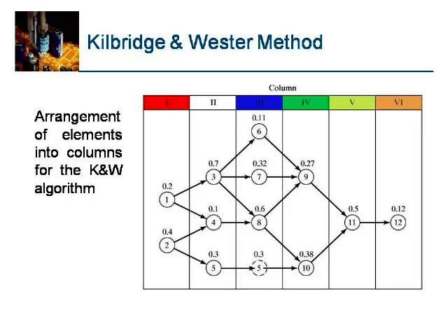So in this you can see here, we can draw lines as columns. This is here, this is here, these elements fall in the third column, these elements fall in the fourth column, like that. After this, assign these elements 1 and 2 first to this station till it exhausts the total time for each station. Till that you can go on adding these elements.